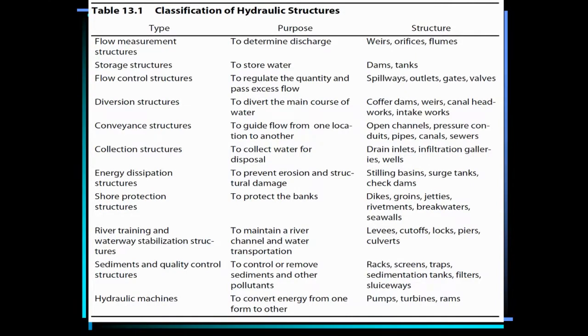The dam stores water. The part of the dam that allows excess water to be spilled over or passed over is called the spillway. So a spillway is an integral part of a dam. Then we have diversion structures. As the name implies, they divert the main course of water. Here you can also use dams, weirs, canal headworks, intake works, and what have you. For weirs, we are going to consider them in this chapter, and we'll discuss their hydraulics at length.